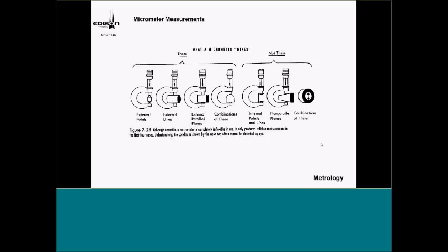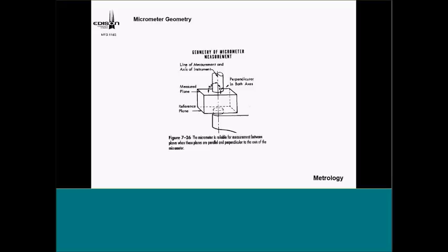The proper way, what we can use it for as far as external points, external lines, external parallel lines, combination, but we can't do some of that inside. And this is where I bring it out. I actually have ball attachments that I will show them how to use, put a ball here and a ball here. But with that, you've got to make sure that you take the diameter of your ball away from your measurement. And again, we're looking at the measure line to the reference line.